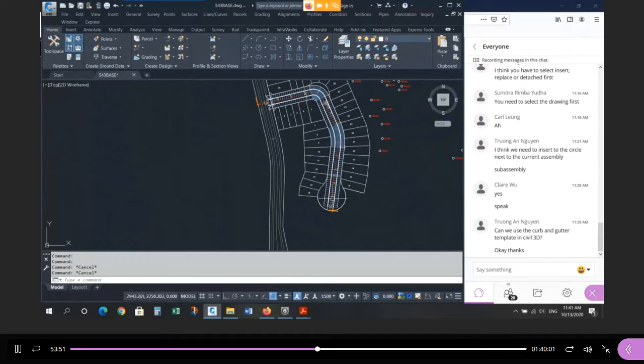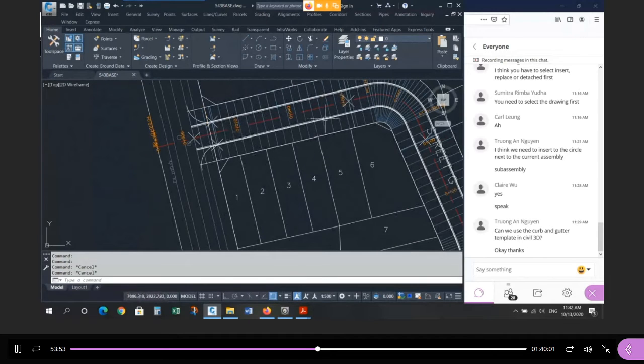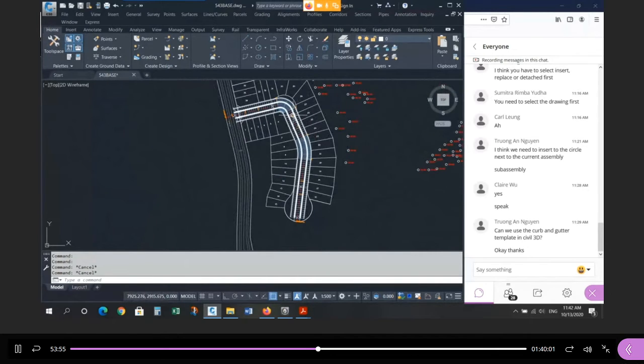So when it comes to this corridor, it's pretty good, right? On the straightaways, your typical 20s, it's perfect, right? Between the elbow and the crescent, everything along here is perfect. Now we have to manage the bulb and the crescent and the intersection. Okay? So like I said before, when you're doing these roads, the standard typical width pretty much takes care of itself. You spend most of your time dealing with these areas where you have these weird widenings, right? Cul-de-sacs, crescents, and intersections. That's where most of your time is spent, right?